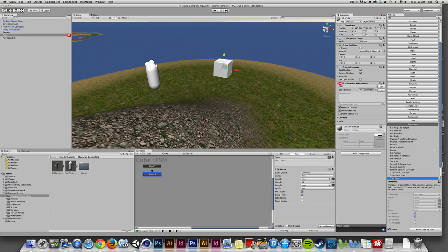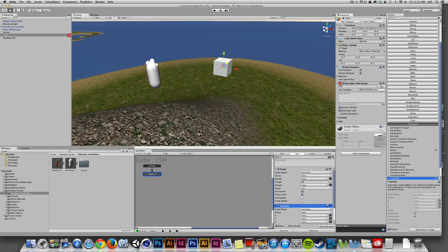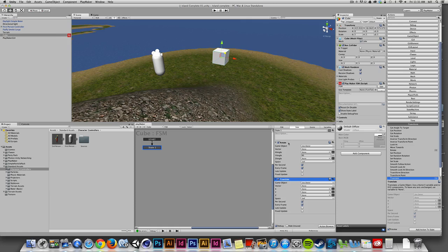Now what translate does, and I'll just double click to add translate, you'll notice that I now have two actions on this state. And I'll just scroll up. And the hierarchy starts to become important here, because the way that Playmaker works is that it'll conduct whatever action comes first, and even if they're simultaneously happening, it's going to activate the first action and then pass it down to conduct the second action. The first action is rotate, and that's starting to rotate 90 degrees along the line.